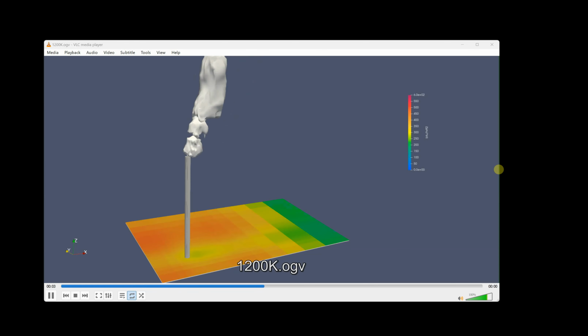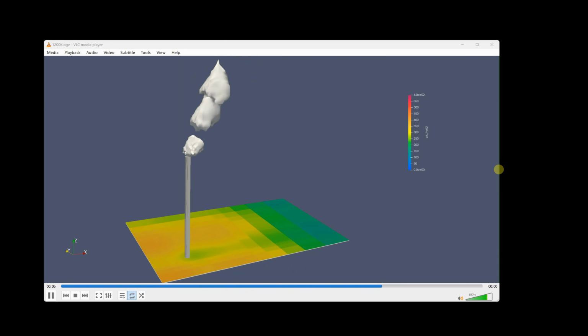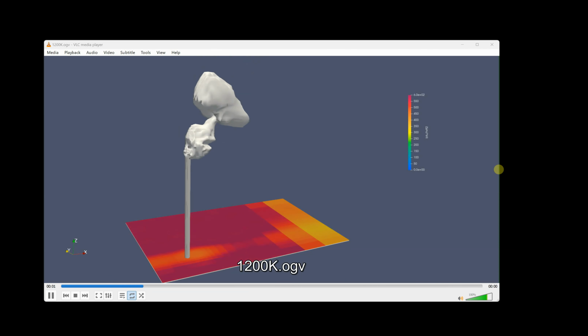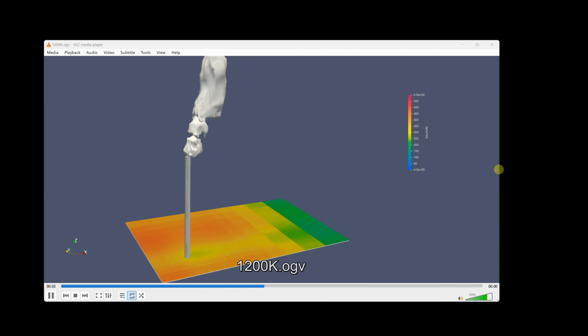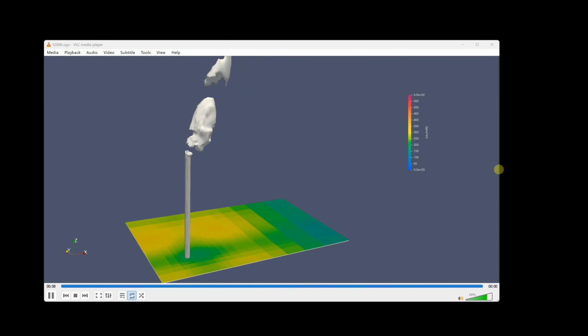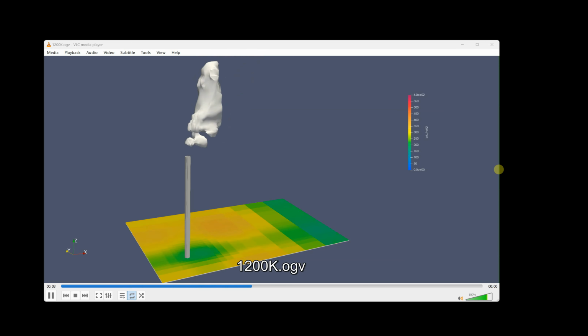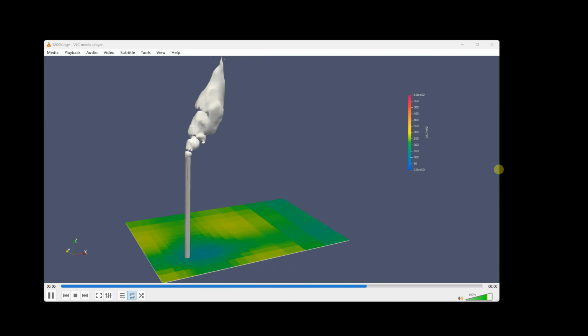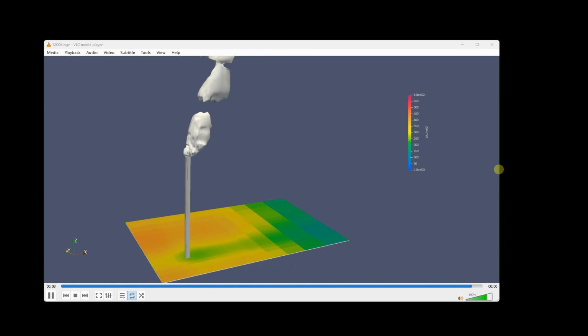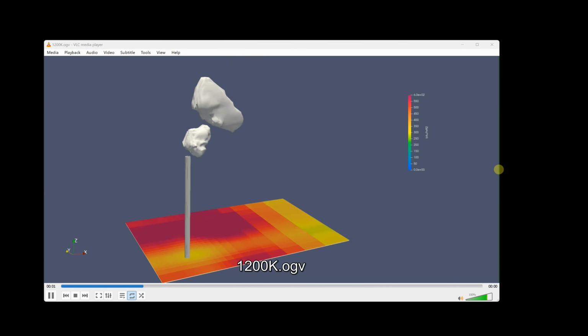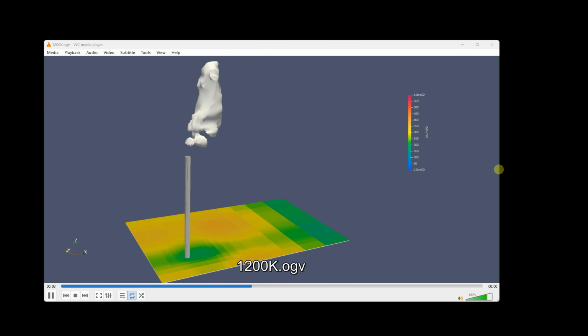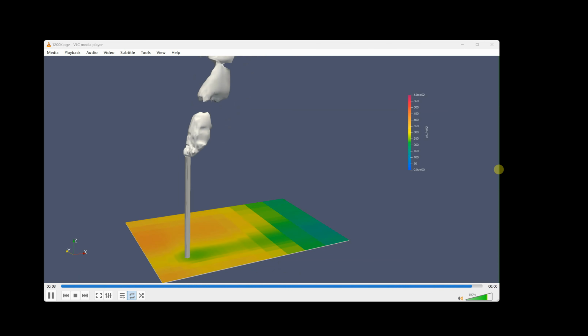Now, the other thing that's somewhat challenging with hydrogen gas is that it is neither optically thick nor optically thin, at least in the dimensional scale that we have of a flare, which is many meters thick. The emissivity of the flare is on the order of about 0.1, and that also is a computationally challenging situation to analyze. Nevertheless, I'll show you how to do it with the C3d code.